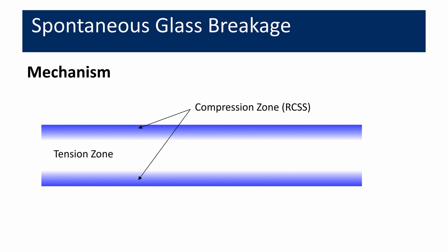Now, as Stephen mentioned before, in tempered glass, heat-treated glass, there's this outer compression zone and inner tension zone. The outer compression zones comprise about 20% of the glass thickness at the surface. The tension zone, like the center, 60% or so.